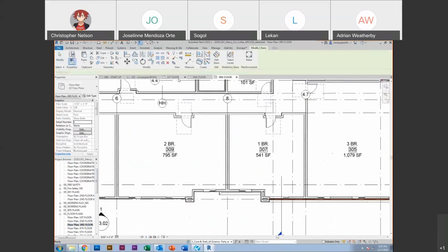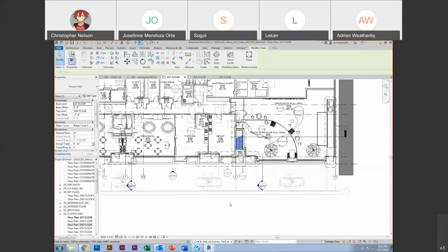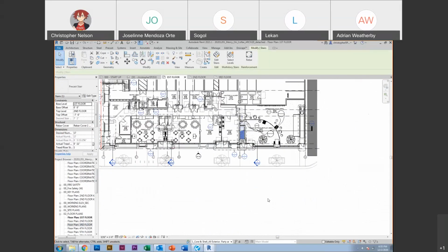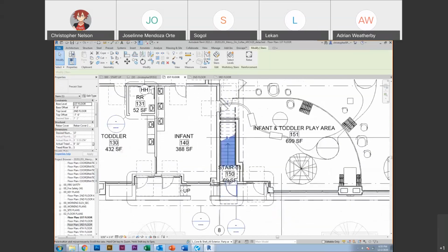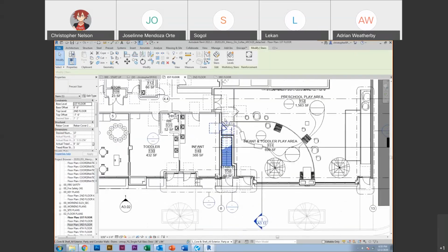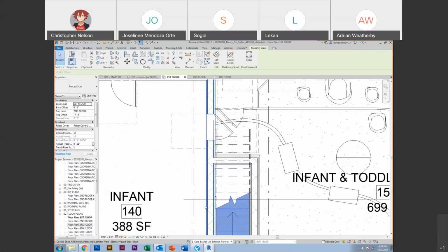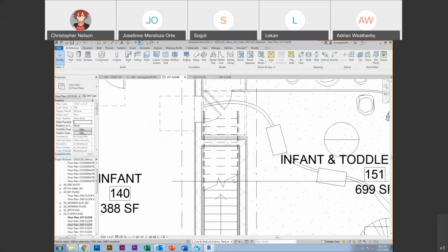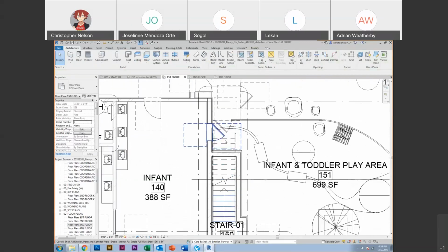So what you'll see is on the ground floor, this blank space down where my cursor is, Colfax. You'd approach, and then you could come in, and then you can come up. So here it's just a straight run, north to south, straight run of stairs. And it gets a little confusing, but after you have this cut line, it's considered above your head, right? I have doors underneath my cut plane, so I need to make sure that my stair is not only above those doors, and clear head height is 6'8" minimum. I also need to make sure I get up to that next level.